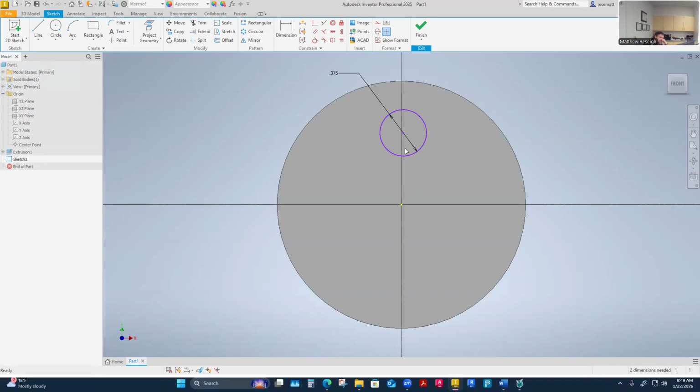So in order to constrain it, I would need to know its bolt circle or a distance off of the center point or something out from an edge. It's definitely going to be centered vertically this way, which I haven't done yet. But I don't think it puts me on a radius outside from the center. For whatever reason, he just decides not to give us a dimension there, from what I can see. Maybe halfway, sure. I don't know.